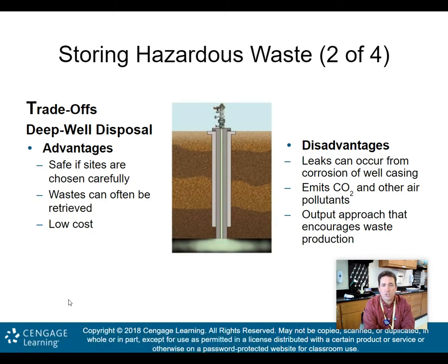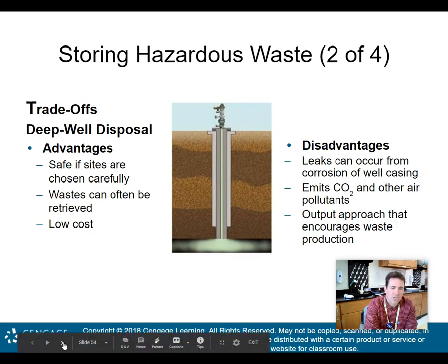So deep well disposal, again, is where we pump the waste way down into the ground. Advantages: safe if sites are chosen carefully, waste can often be retrieved if we have to, and the cost is rather low. Disadvantages: leaks can occur from corrosion of the well casing, and that would obviously leak toxic substances into your groundwater. It does emit some carbon dioxide and other air pollutants. And it encourages waste production because we have a place to store it. We want to try to discourage waste production somehow.